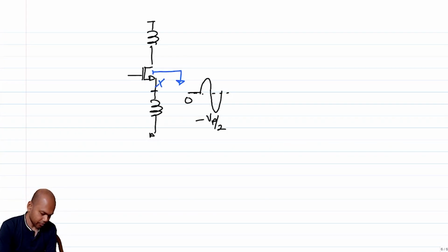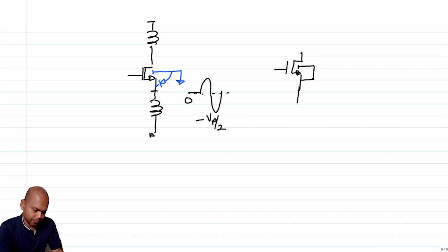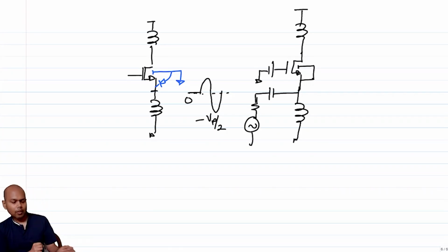you have essentially this parasitic diode which is inbuilt, and if the source voltage now goes below one threshold voltage, or rather the cut-in voltage of the diode, then we have a problem, right? So that is why if you have to use this type of topology, you have to ensure that you connect the body to the source all the time. This becomes your input. Okay.